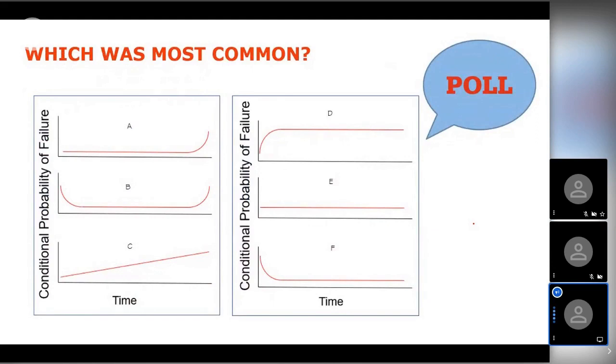They actually found that instead of being this one failure profile, like I just showed you the classical failure profile, the A in this graph here, rather than there just being this one typical profile, they actually found 6. The first one I just talked about, the classical failure profile, more or less random throughout its life, and then gets to the wear out zone at the end where it increases in the chance of failure.